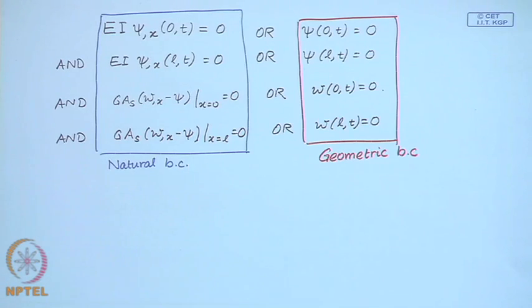Now, this Timoshenko beam still makes an assumption that the cross section which was plane before deflection remains plane, though it need not remain perpendicular to the neutral fibers. So, this is a kind of limitation of Timoshenko beam, but then you can very easily relax this by introducing more complex functions for your deflection field. So, let us review and see what can be done.